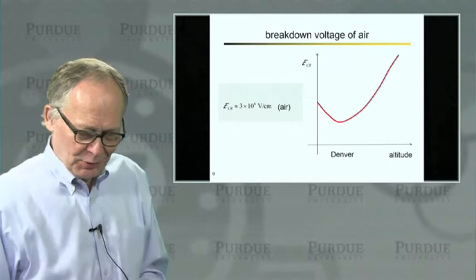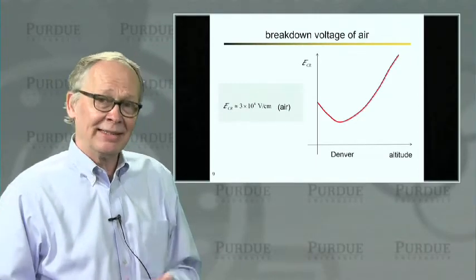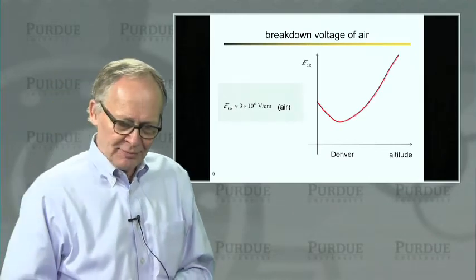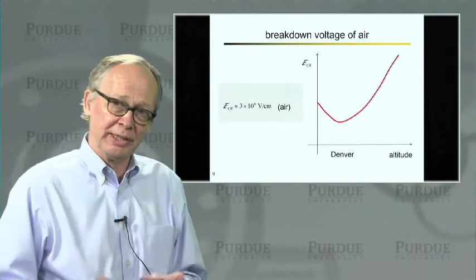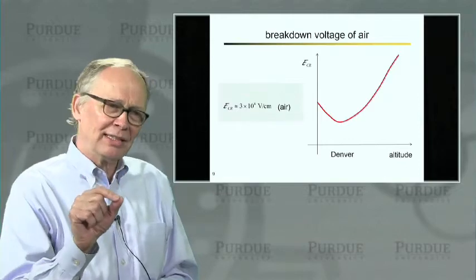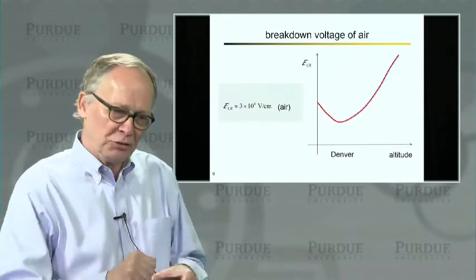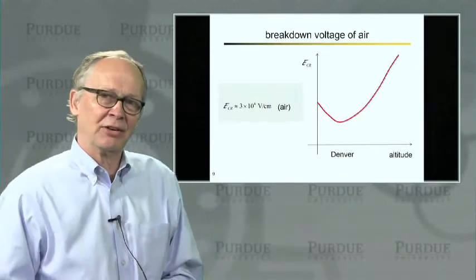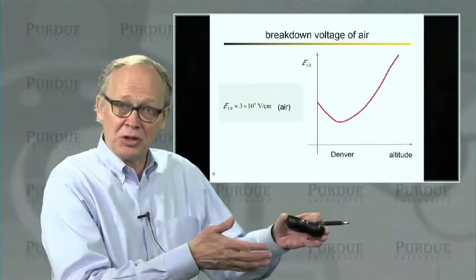So the way we sorted this problem out is we remembered our electromagnetic fields. There must be some high gradient somewhere giving us some sharp electric fields. We came in at night, turned all the lights off, flipped on the switch, and saw where the biggest spark was. Then we turned the lights on, and we looked at that spot, and we found a very sharp piece of metal. Took the file out, smoothed it out so we could round it out and reduce the gradient. Turned the lights out again, flipped on the power. The spark came somewhere else.